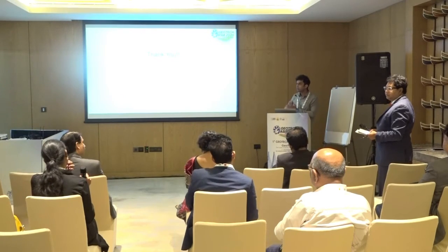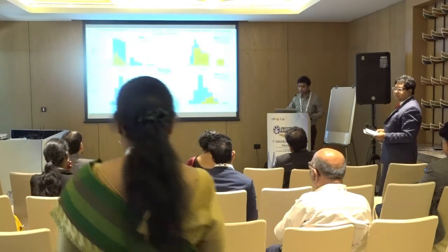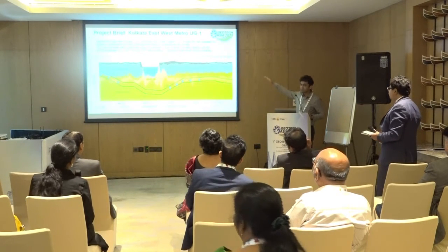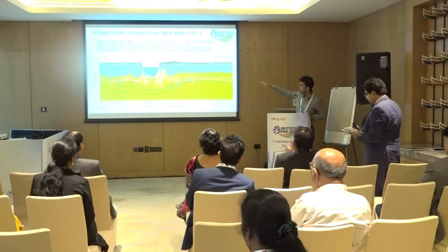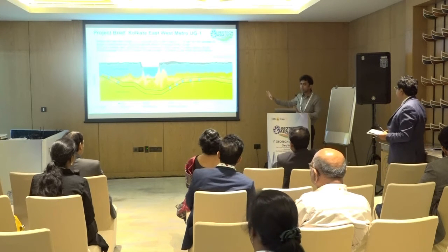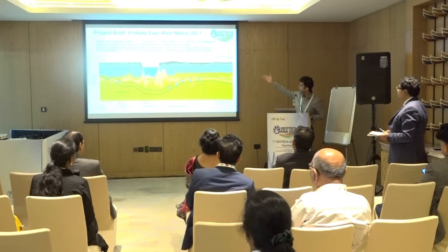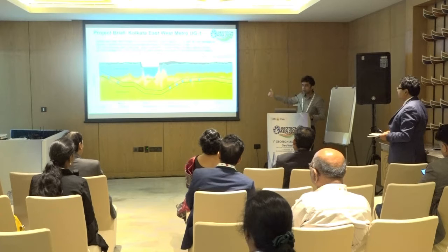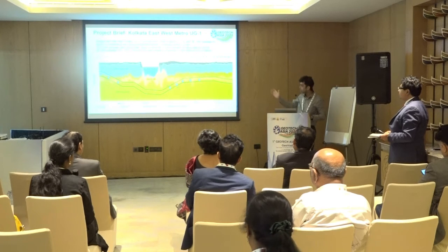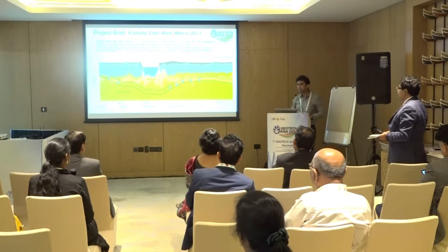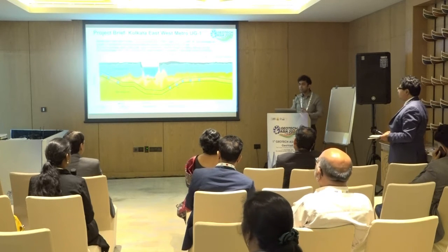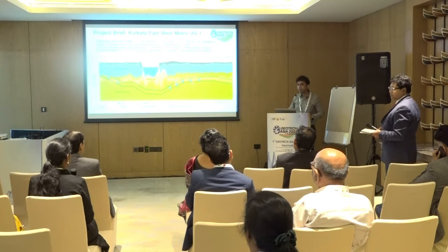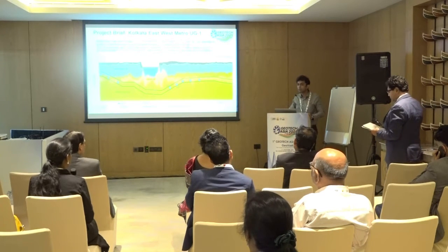Earlier, as we can see, the geological context is similar. Over here, it is very homogeneous in context. So we have test results at different locations, and it is more or less homogeneous. There's soft clay which is located at different locations, and there's stiff clay which is located at the lower depths. So the standard values were taken at different locations and considered for this. Not exactly at the same location, but since there was homogeneity regarding the soil strata along the length, they were considered for correlating the values.